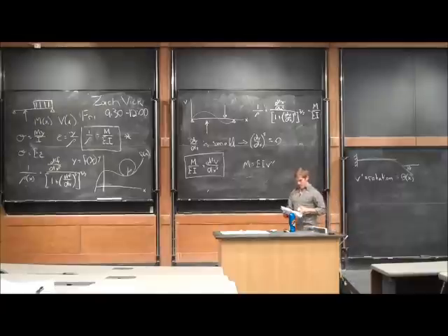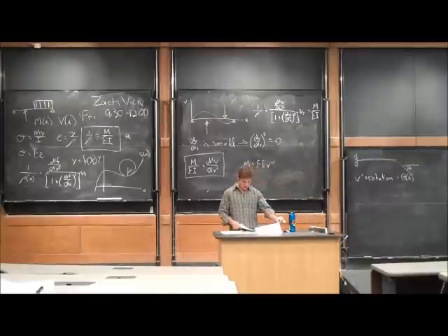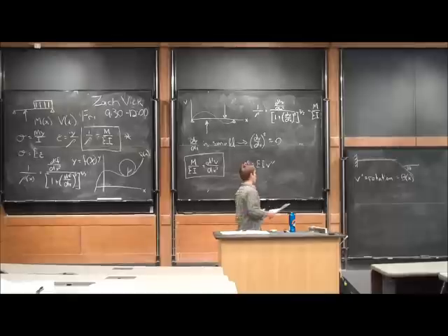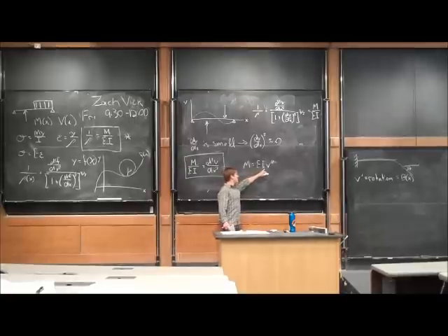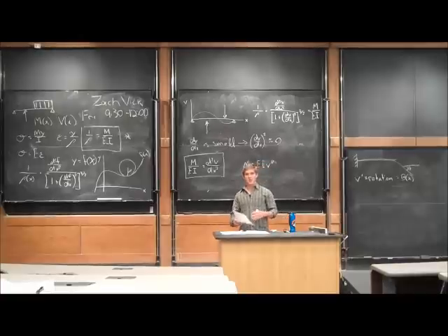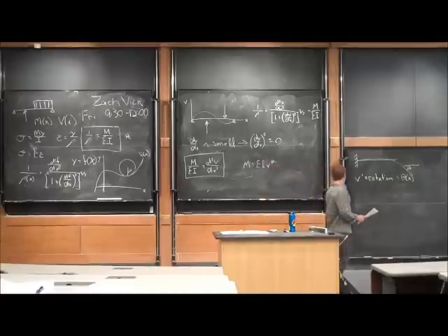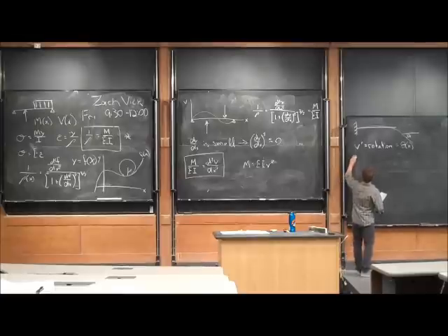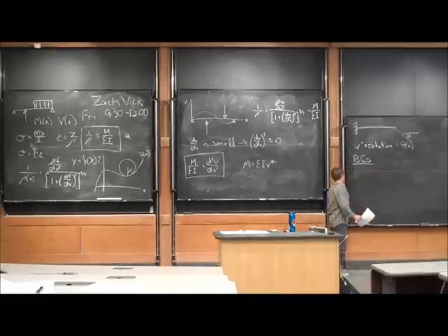So based on that, let's look at how we would solve this equation. If you remember equations like this from Dynamics, that's a differential equation. We have a second derivative here, so that means we need 2 boundary conditions to solve it. So if we're going to apply boundary conditions to an actual beam, how would we do that? That really depends on the situation you're looking at. If we're going to try to find boundary conditions for this equation, that's all due to how the problem is set up.